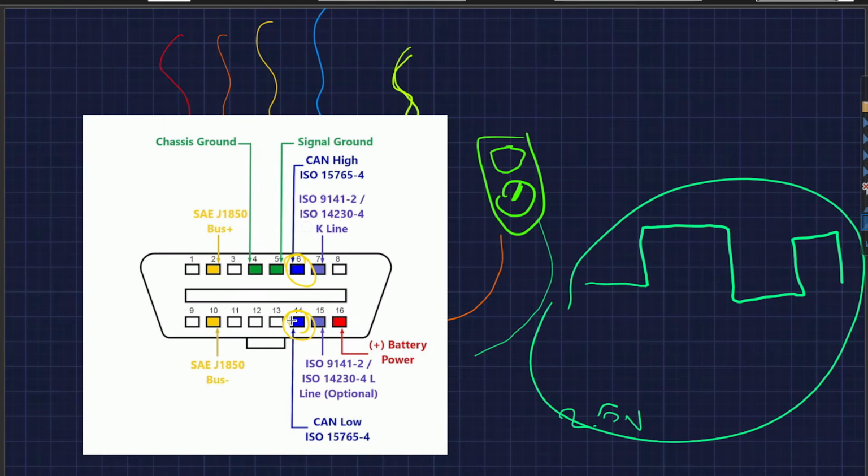This is standard high-speed controller area network, also known as high-speed CAN. This is usually where beginners start, and that is fine. But understand this clearly: not all controller area network buses are exposed through the OBD2 connector. Many internal buses are hidden deeper inside the vehicle.